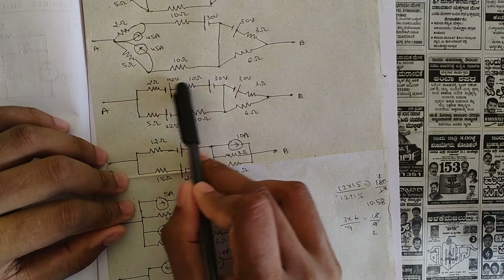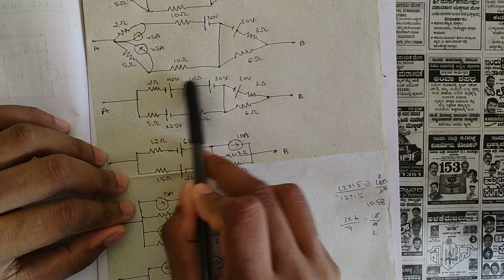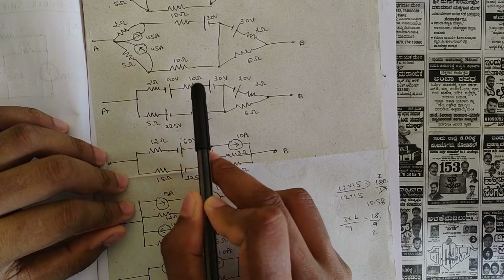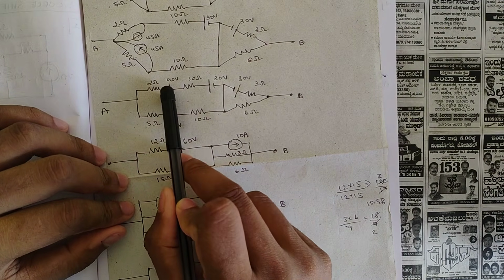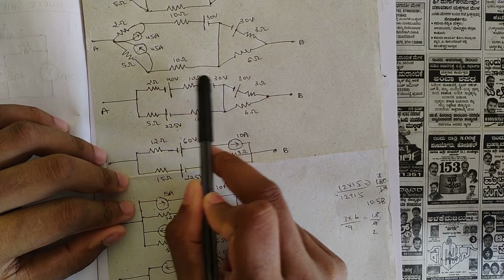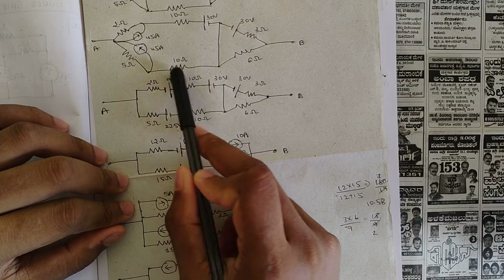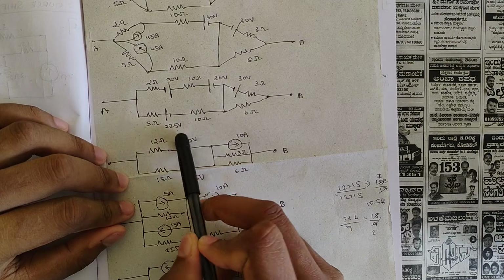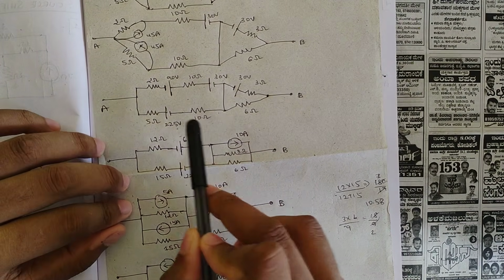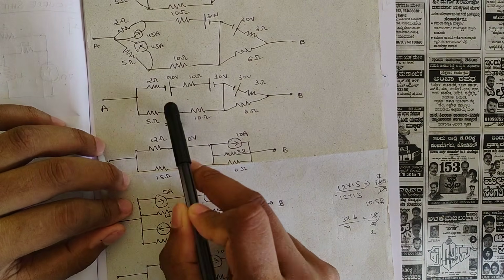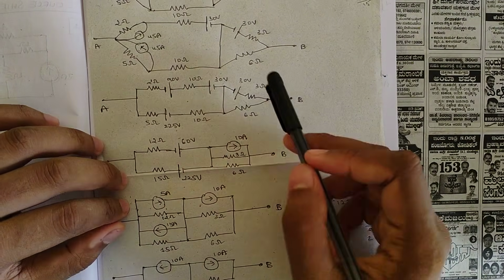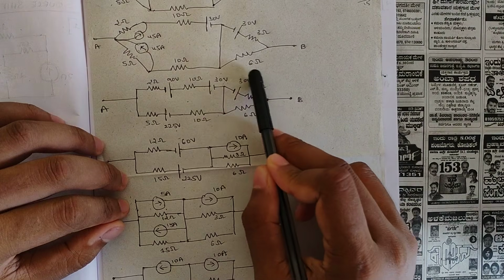Then these four components are in series here in this line. So 10 ohm plus 2 ohm, that would be 12 ohm, and 90 volt and 30 volt have opposite polarities, so we need to subtract, and the greater polarity is for this minus plus. So I've kept this minus plus, and 90 minus 30 is 60 volt. So 5 ohm plus 10 ohm is 15 ohm. This 225 volt I've kept as it is.